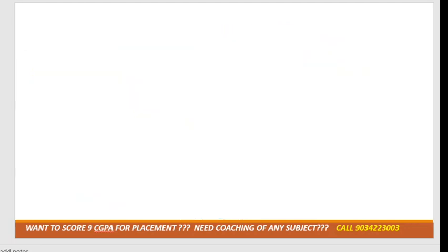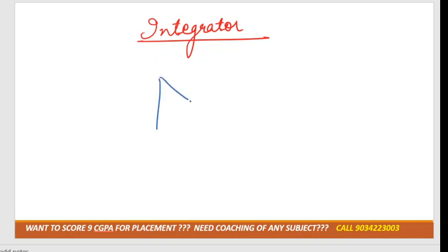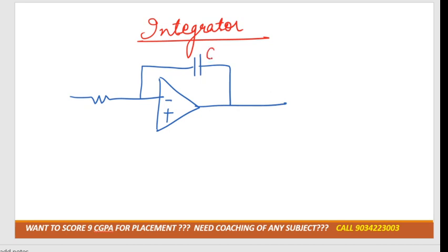Okay. Next case is that the op amp will work as an integrator. As its name suggests, there is an integration for this case. We'll draw the op amp. Again, we'll connect with the negative terminal, and then instead of a feedback resistor, we'll use a capacitor as feedback, which is why it is denoted by CF. CF is for the feedback capacitor. There is a resistance R, and here we are providing the voltage V in. The other terminal would be grounded, and the positive one also would be grounded. Here the output voltage is represented by V naught.